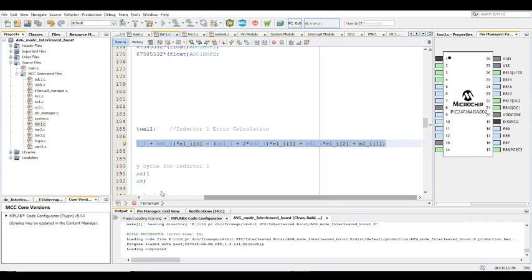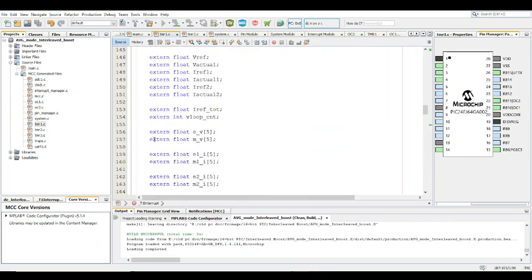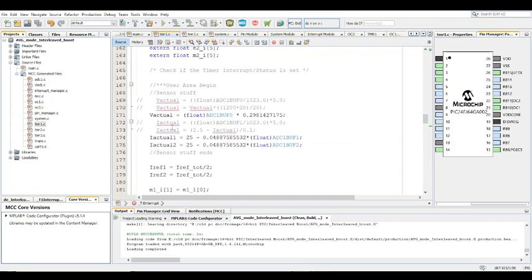All right. So at first you have to get the readings for the actual voltage, and then for the current for both inductors, I actual 1 and I actual 2. And so basically here, this value represents the bigger resistor in this resistor divider, and this is the smaller resistor. And once you do a calculation of these two lines up here, you come up with this particular line. This is not included because of controller processing time. To add those takes more time than to just execute this line.